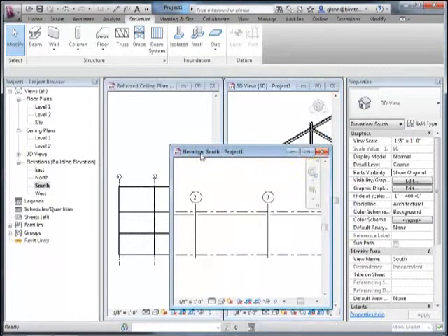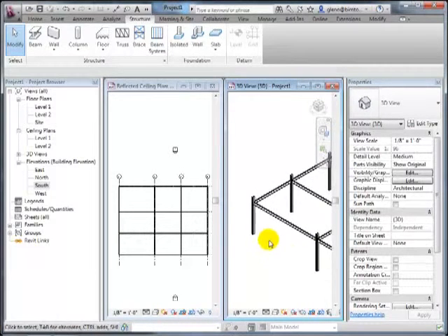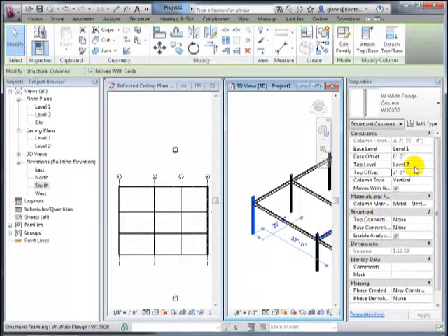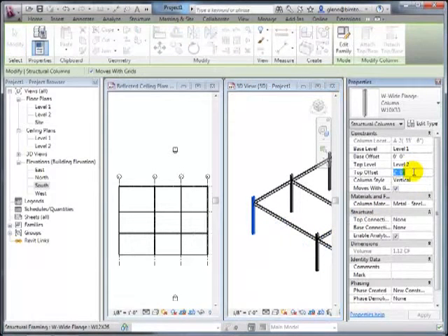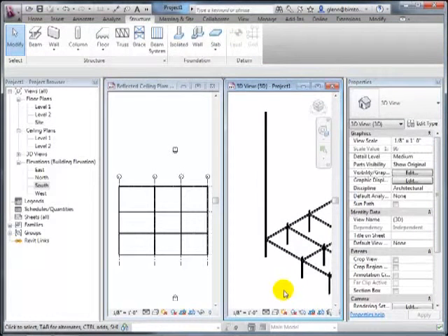The good point to get about this is you want to model things as accurately as possible to how it's actually going to be built. What not to do, and a lot of people will start by doing this, is say, I just need something that's 100 feet tall, so they'll put the 100 feet in, and it'll look okay in the model. The problem is, later on, whoever's going to estimate using your model, whoever's going to try and build using your model, will have trouble because they'll have your parts. What's that?